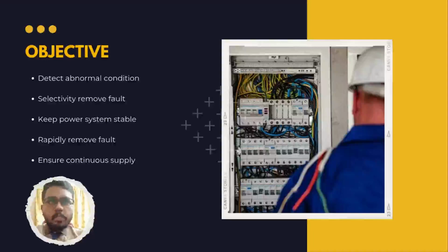Reducing the number of equipment disconnections is necessary to isolate the malfunction from the system. The fourth objective is that the protection needs to be steady enough not to activate when the connected equipment is carrying the maximum rated current, which might be a temporary value, yet sensitive enough to activate when a fault arises under mild fault conditions. The last objective is to operate reliably and quickly enough to remove the fault from the system with the least amount of damage to its constituent parts.